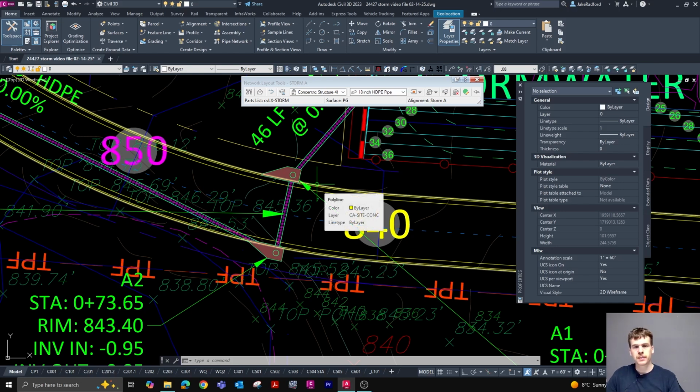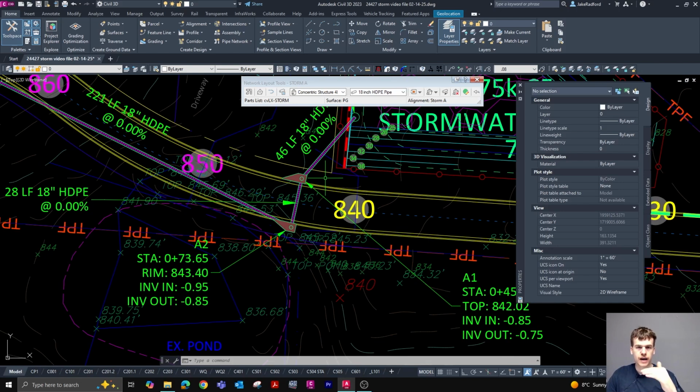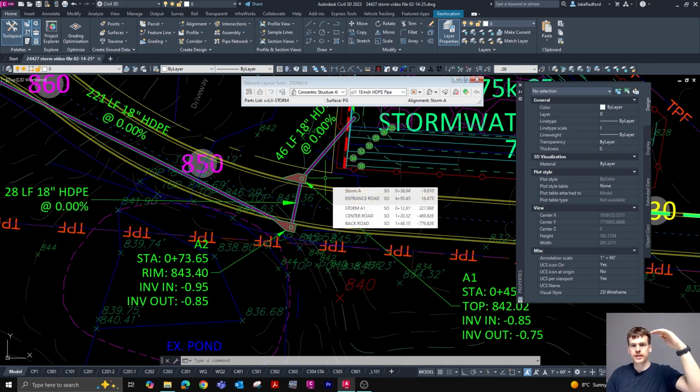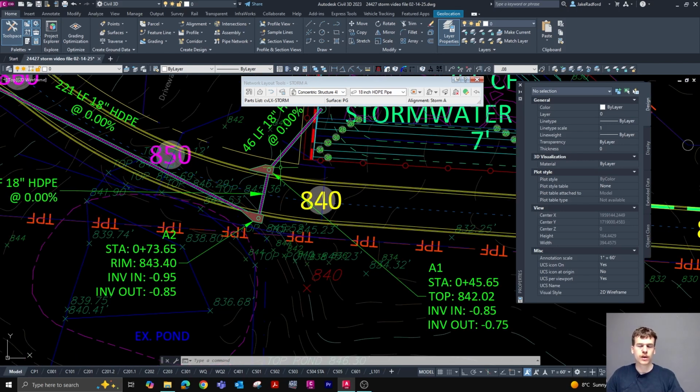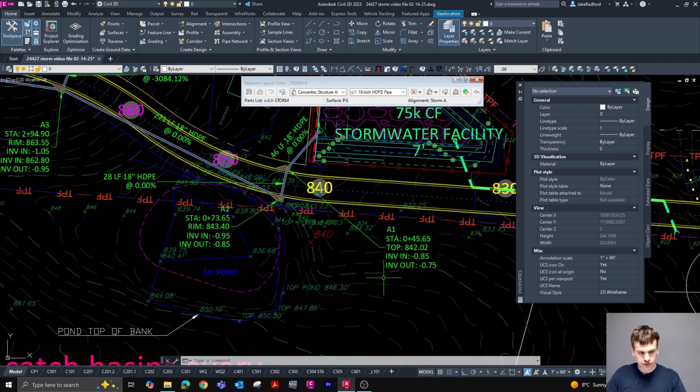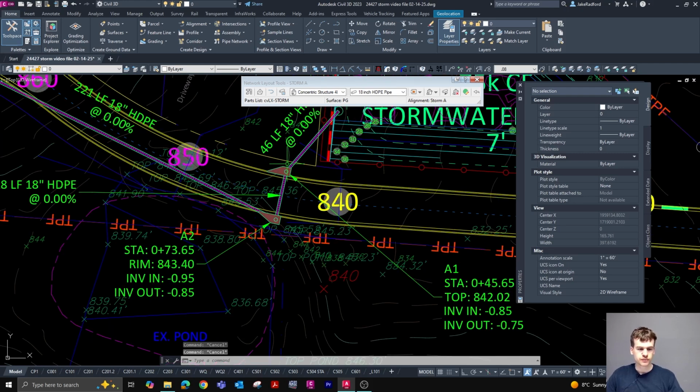Well, if you have a pipe, pipes have tops and bottoms, so the invert is going to be the bottom elevation where water can first start to come in. If water is all the way up at the top of the pipe, then it's all the way at the bottom of the pipe too. So we have terms for the bottom of the pipe, invert, just like we have terms for the top of the pipe, which is crown. So the inverts are the key information because that's when water will start to come into the pipe.